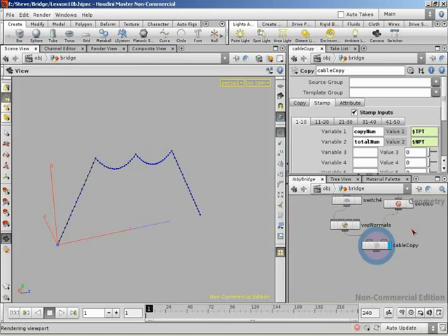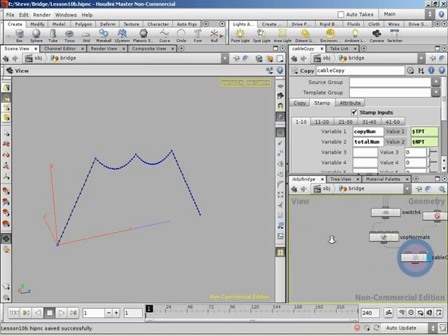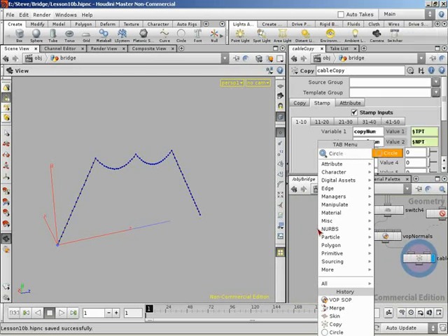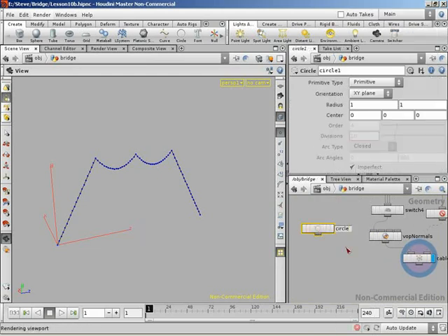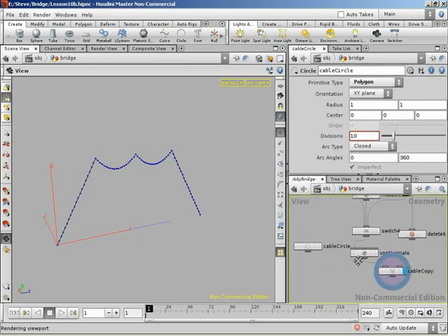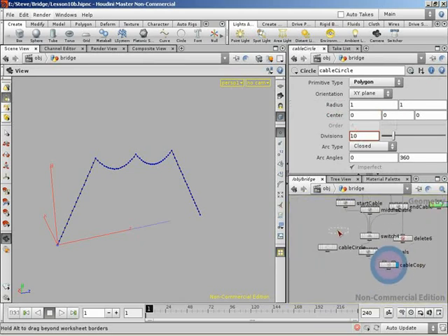So with that, we can now create a circle and copy it to our cables. Okay. So let's drop in a new circle, which I will name cable circle. And let's set up a couple of, firstly let's set this to polygon, and let's set up a couple of controls on our master control to specify the radius and the number of divisions. Makes sense. So if we find our master control, let's bring it down where we're working.